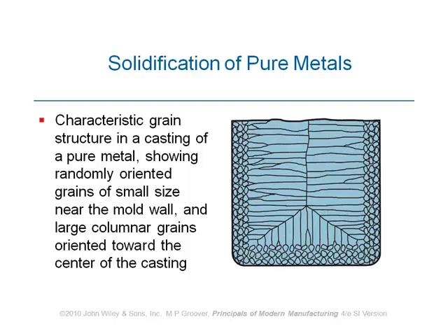And why does it happen like that? Because the first grain, which has solidified somewhere, say for example here, grows inward. The reason is that the hot region is inside at the core of the material, which is here. As the first part of the grain has solidified, it grows along the direction which is still at a higher temperature.